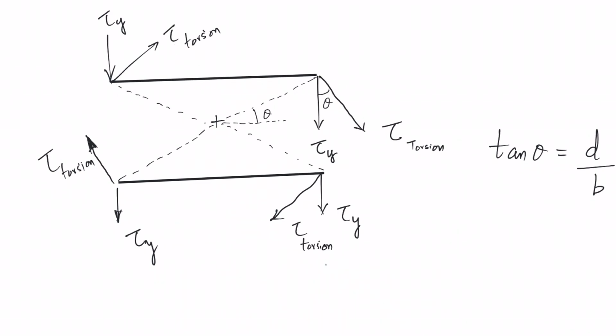I have shown it only at 4 salient points, and those will be perpendicular to the radial distance from the CG. Makes sense? You have a disc under torsion, a circular bar under torsion; your shear stresses will act tangential. These are all basic things which we learned. So your shear stress acts tangential as shown over here, over here, over here, and over here.